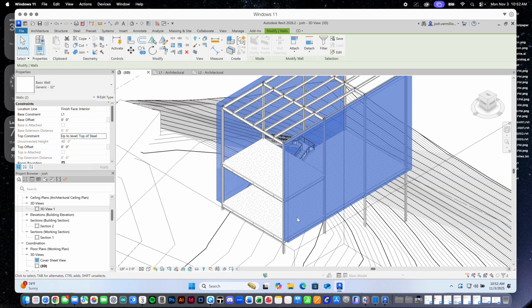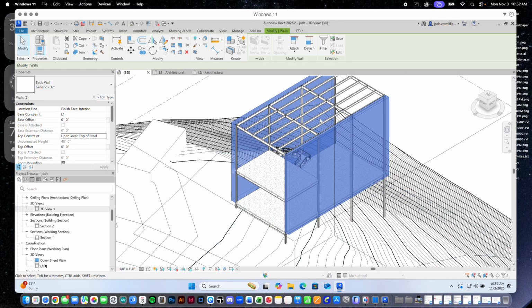And let's go to the 3D view. You'll see that. Now, we'll also see in the 3D view that we need to offset where the bottom of this wall starts so that it slides past and actually covers the edge of the slab and the structure and things like that, right? So in other words, it becomes not only an envelope around space, but the fascia around the structure that's behind it as well, okay?